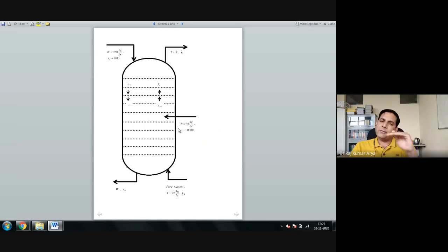Because you have already fed it there. Now from here you are getting y11, right? When you come to the 10th plate, you have y11 coming in. Practically, whatever is coming with the toluene feed is the composition of this pure toluene. So when you feed pure toluene, how much will y11 be?